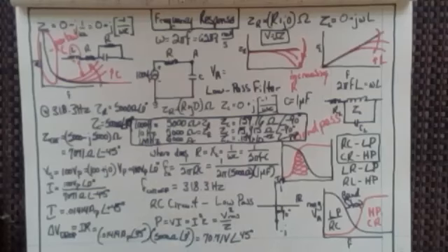Now we could break that up too. You're probably thinking to yourself, well, I can already see that at 45 degrees, if I wanted to turn this back into a complex number, rectilinear, a plus jb notation, that I really only have to multiply 70.71 times the cosine of 45 degrees, which, by the way, is 0.7071. So 0.7071 of 70, doesn't that give me 50? That's right. 50 volts plus j50 volts. That's what we get. So that's my voltage drop.